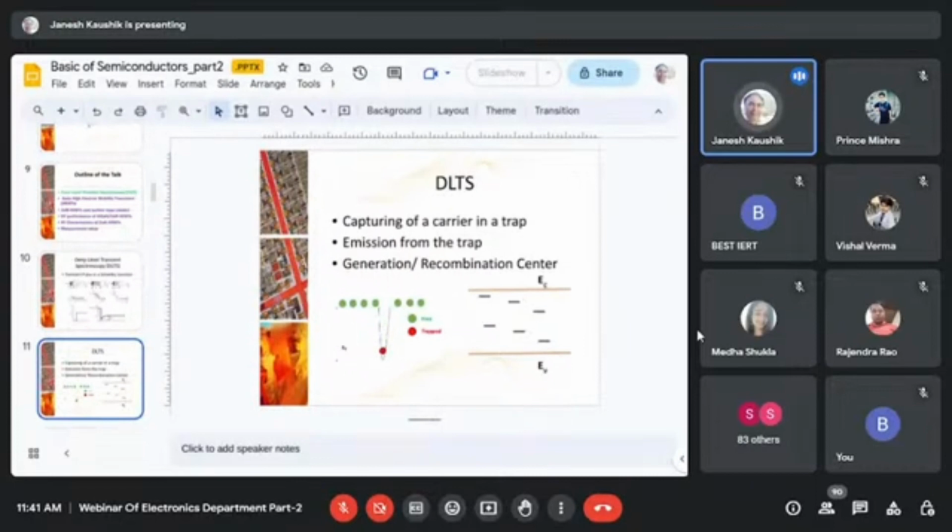So it is an energy level somewhere in the band gap that you can see in the band diagram. And as I mentioned in the last lecture, a charge is called trapped when the capture rate is more than the emission rate. Here we always talk about rates. It's not a constant phenomenon, it's dynamic in nature, with emission and capture constantly taking place.